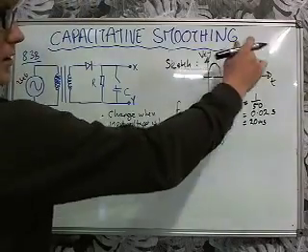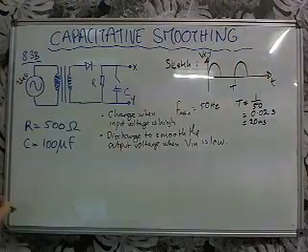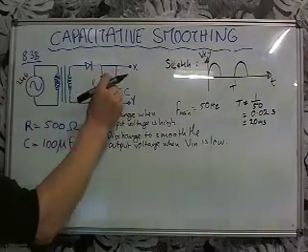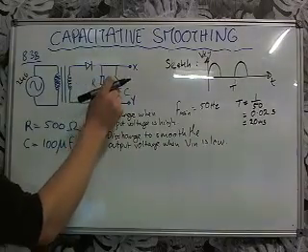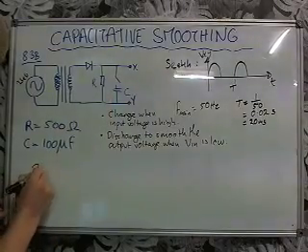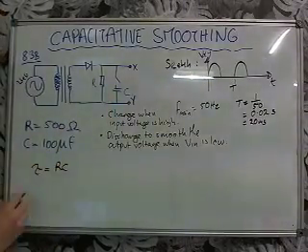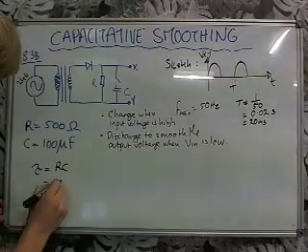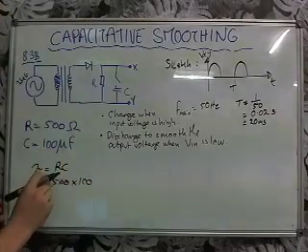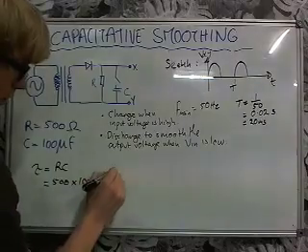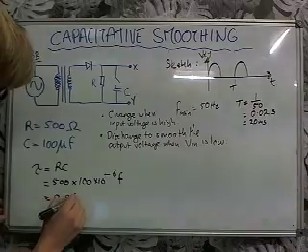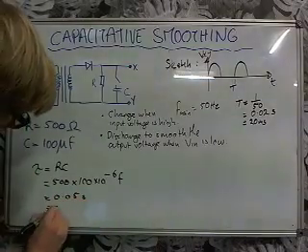Now, they ask us to calculate the time constant of discharge of this capacitor. Okay, so it'll discharge through this resistor, and we know the formula tau, time constant, equals RC. Okay, and so that'll be 500 times 100. Now, 100 microfarads is times 10 to the minus 6 farads, equals 0.05 seconds or 50 milliseconds. Okay, so the time constant is 50 milliseconds.